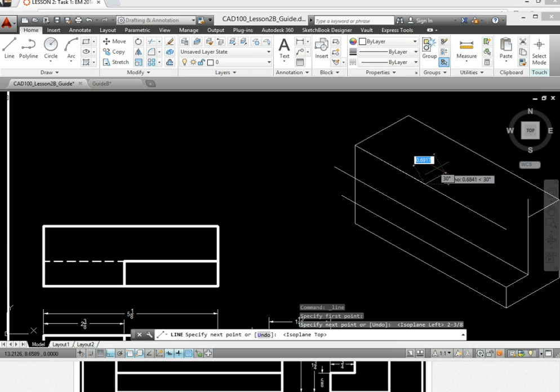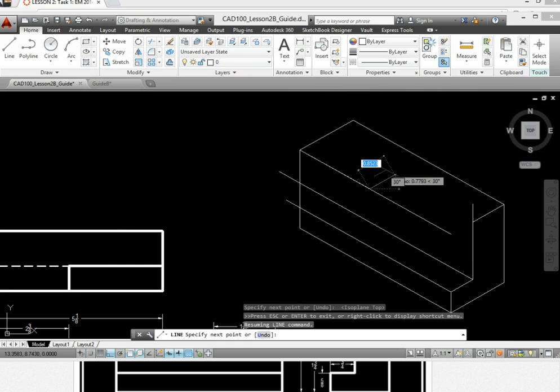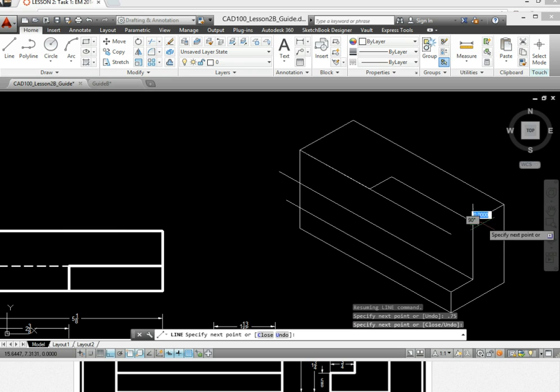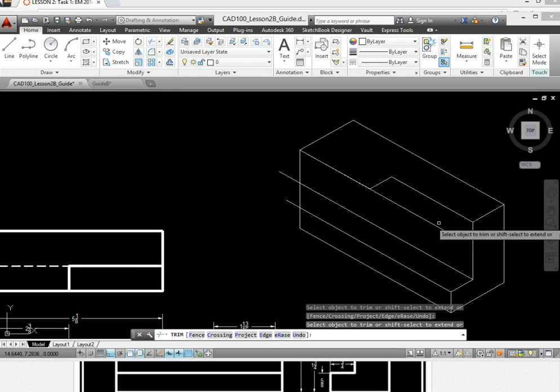Wrong direction. F5 should be the top view. There's a top view right there. That depth right there was 3/4, just like we read before. Here, same 3/4. So point that way, type in 3/4, so 0.75. And of course it would work perfectly because we drew this 3/4 over here also. Let's do some more trimming to clear up some of this stuff.